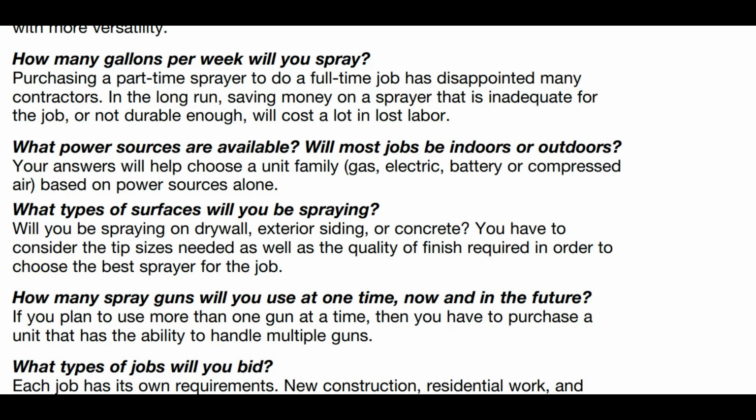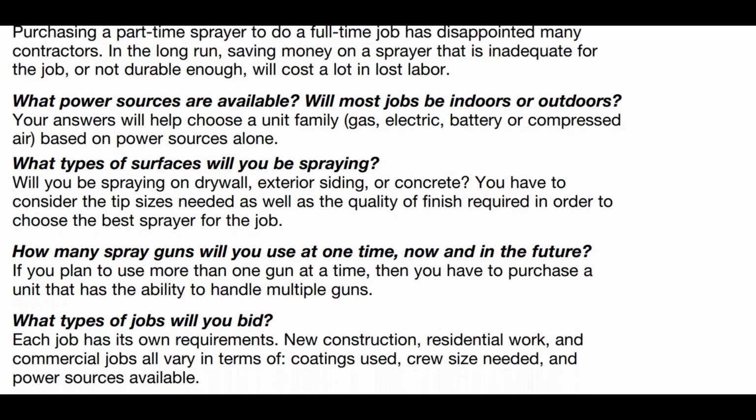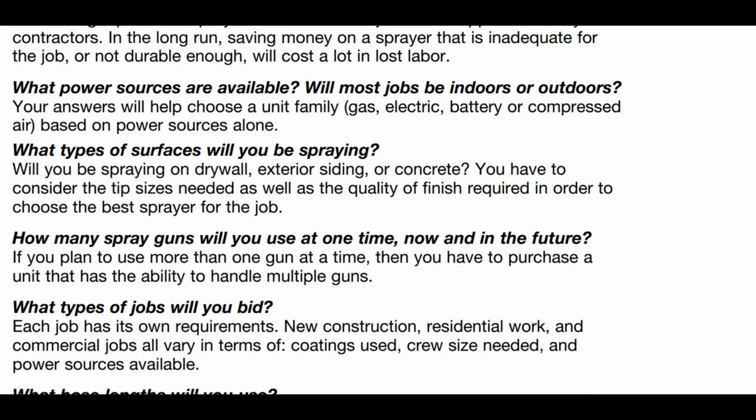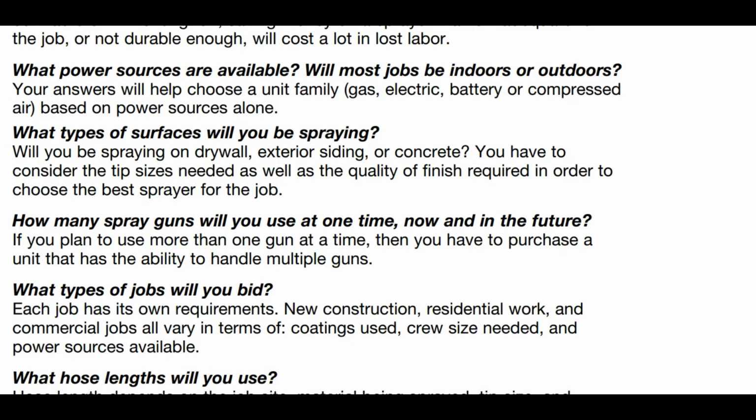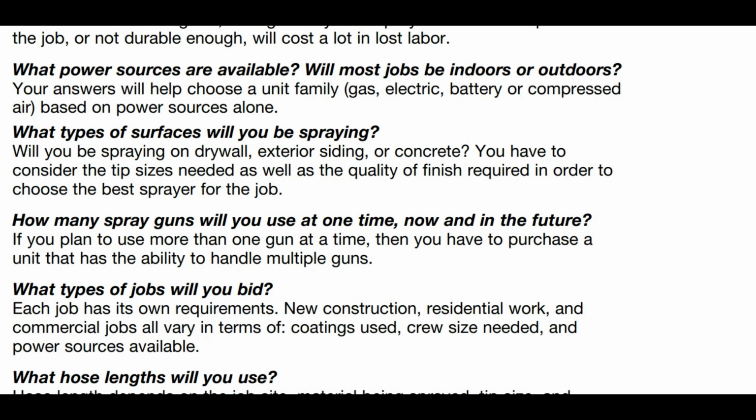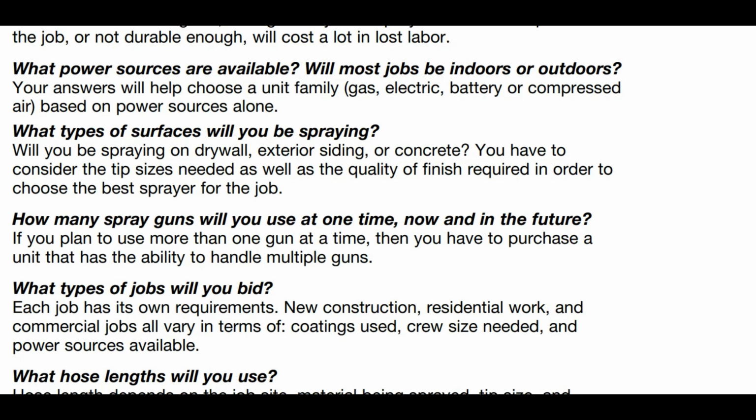What power sources are available? Will most jobs be indoor or outdoor? Your answer will help you choose a unit family based on power sources alone. What type of surfaces will you be spraying? Will you be spraying on drywall, exterior siding or concrete? You have to consider the tip sizes needed as well as the quality of finish required in order to choose the best sprayer for the job.